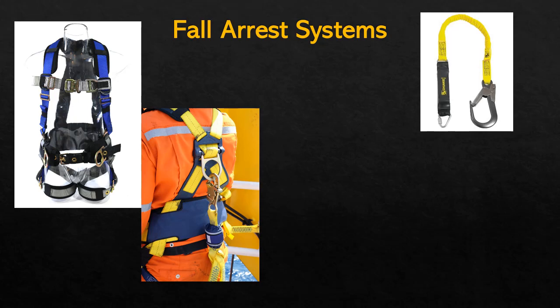What you see here with the lanyard as well is that once it gets force loaded, it will elongate significantly, and when that happens, it can't be used again. Basically, all the components of a fall arrest system, other than the anchorage point, are designed for single use only. Once they've absorbed the shock and saved the life of somebody from a fall hazard, they can't be reused at that point.